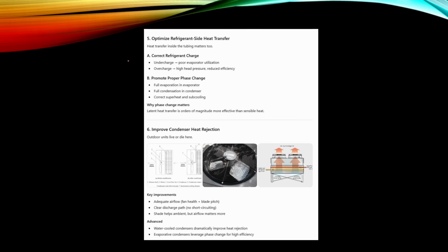One important question is, of course, the heat transfer inside the pipe. If we have a refrigerant case, then as time goes by there typically is some leakage and some coolant escapes, so we end up in an undercharge situation, and then the efficiency will go down.